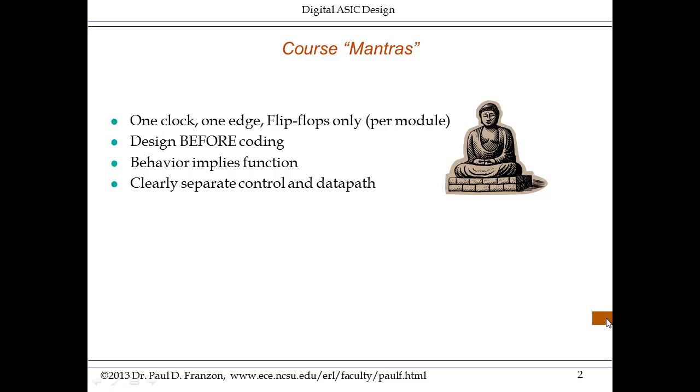This also allows me to introduce what I like to refer to as the course mantras. Mantras are, of course, a term used in religions for things you say over and over again because they're true. Well, these are the truisms for this course, and you'll be tired of these mantras by the end of this course. These are the four mantras: one clock, one edge, flip-flops only. Design before coding. Behavior implies function, and clearly separate control and data path. This module addresses the first mantra: one clock, one edge, flip-flops only.